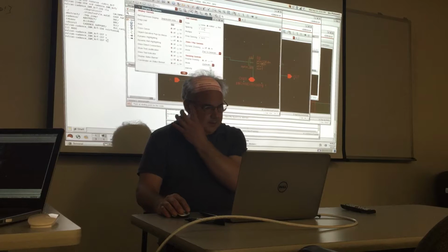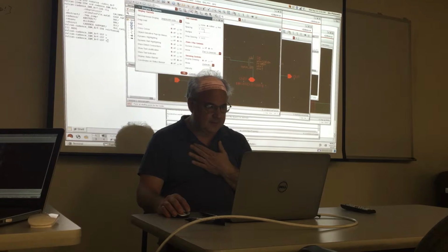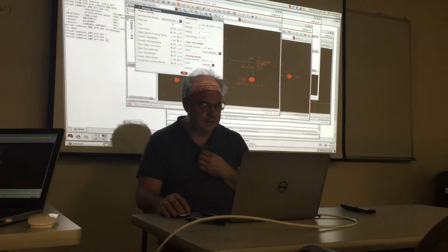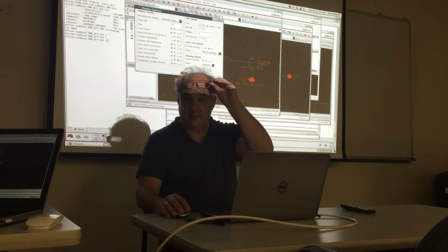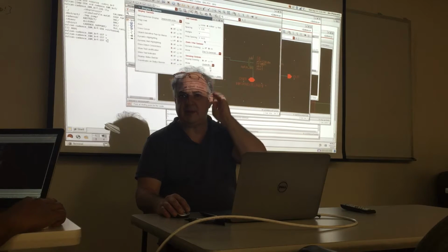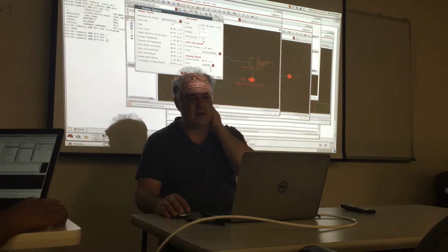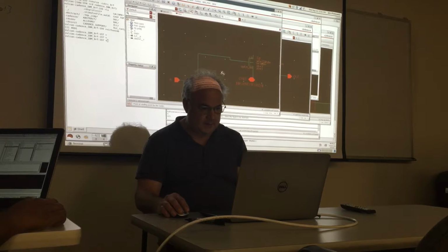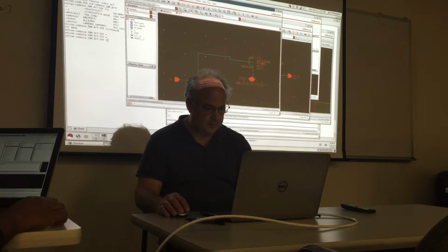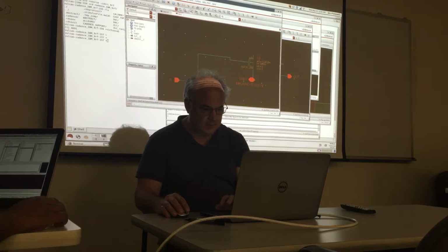Please make sure that the spacing is set to 0.125 and the snap is set to 0.0625. Are they the default? Yeah, oh, that must have been in my CDS environment file, which is great. Don't change those. You create a nightmare. Those seem to work pretty well after experimenting for a while.